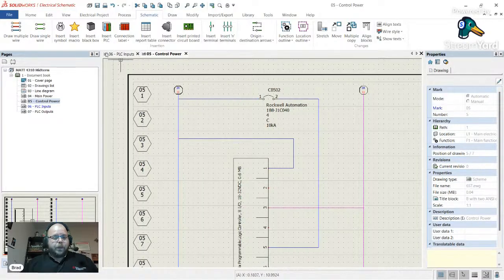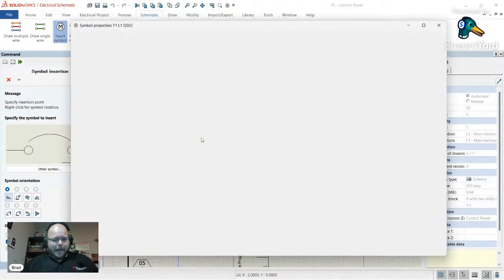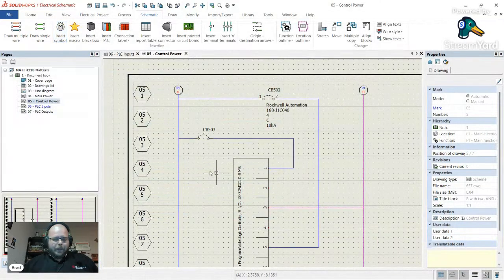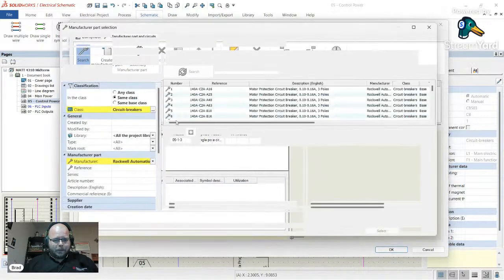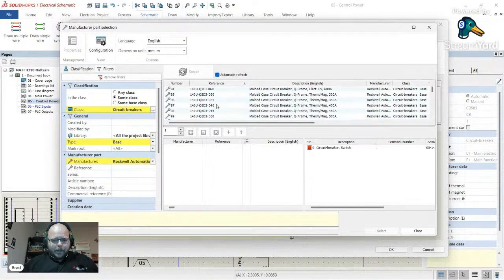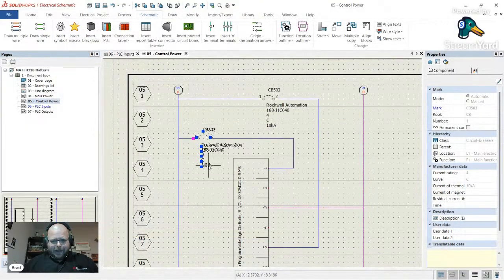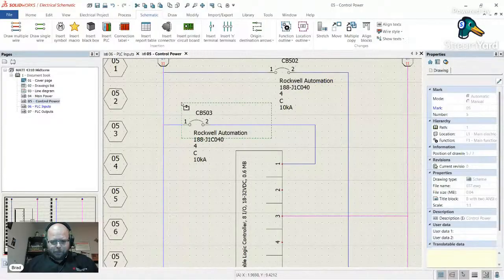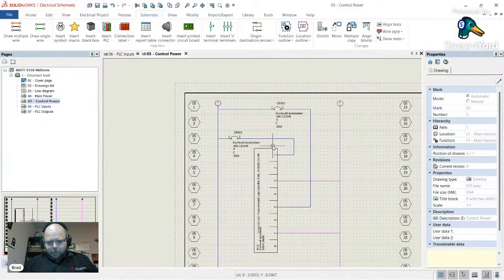I want to protect both of those power supplies. I've got a positive wire going to two different places, so I'm going to protect them both. I would look in that manual, probably not that manual, because that manual didn't have a whole lot of technical data. It was all about programming, and we were on the 188. But I would find the manual, figure out what the max draw on each of those is, the module and the SA power, and protect accordingly. But again, for this, what I'm doing here is fine. I would accept this from students for this assignment. Get rid of that little wispy of a wire since I moved it.